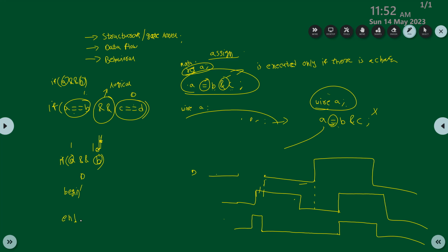You gave the condition A, B, C. It means if any change occurs in A, B, C, then only it will enter into the always block. But with the assign statement, even though there is no change in B and C, A keeps on updating with the values, so it can hold the values. But if you declare A as a register, then the output you get in both cases is the same. If you declare A as a wire, then there will be a difference.